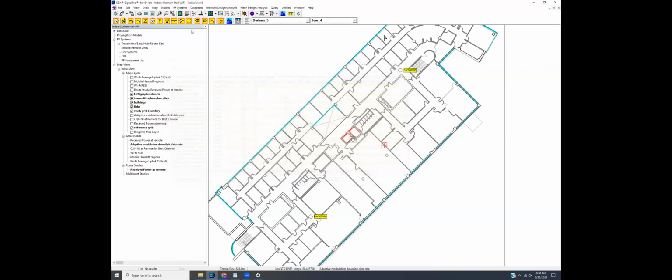And so I would choose those access points and drop them down here. Oh, sorry, that's my access point button. I would drop those down here on the map, just, you know, plug and play that way. Or again, I could create a list of candidate access point locations across this building and have it go through and select a collection of candidates to try and get coverage across the building. That automatic site placement feature works with either outdoor or indoor propagation models and use cases. So if we're trying to cover the inside of a building and there's a bunch of known locations where you could put an access point, we can plug those in and let the automatic site placement go.